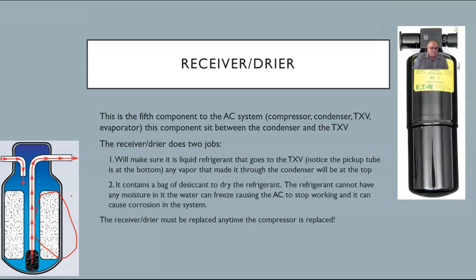But this desiccant is designed to actually remove the moisture from out of the refrigerant. If there is moisture in there, when it gets to the TXV it gets below freezing and it's just going to ice up and plug up the system. And so what you're going to end up with is an AC system that starts, works for a little bit, and then stops until that TXV warms up enough and melts the ice inside there, and then it'll work for a little while, and then it'll stop again because it keeps plugging up with ice.